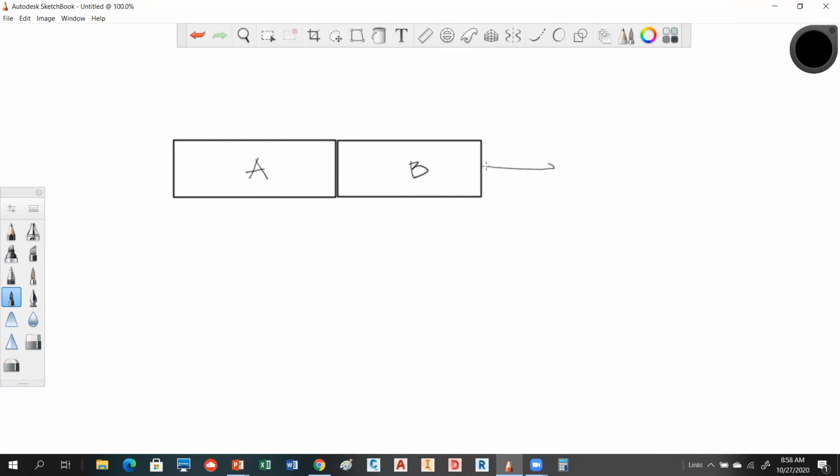So that's what we're saying. Then when we apply a load P on this, the loads are going to be different, well, depending on what you're doing here, but they experience loads differently because you have a modulus of elasticity for A, which will not be equal to the modulus of elasticity of B. So those will not be equal.